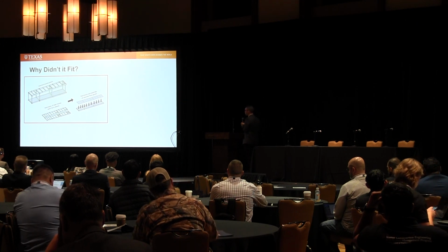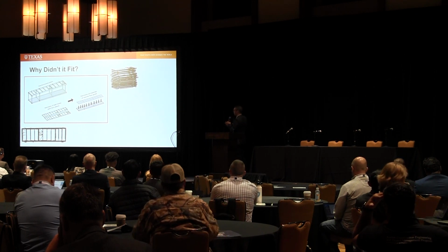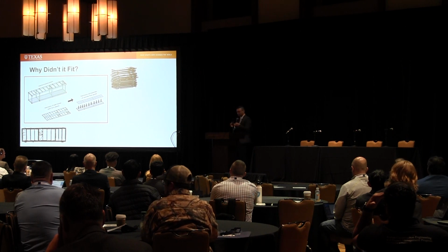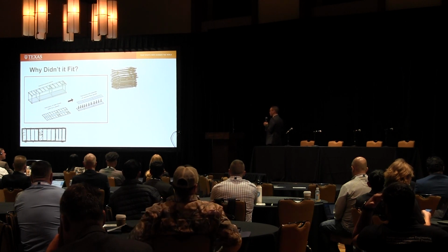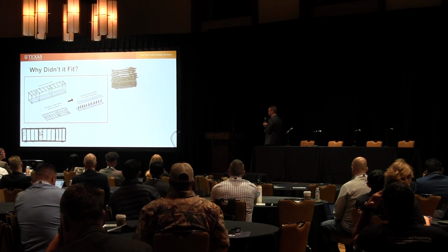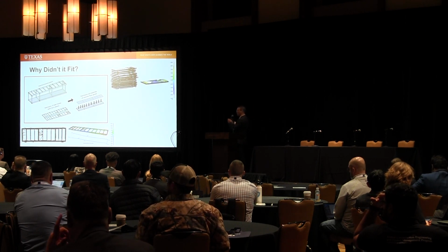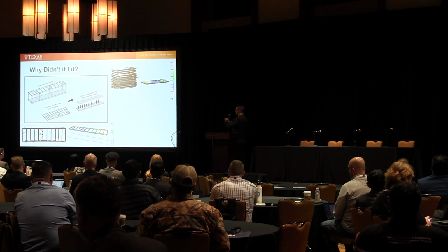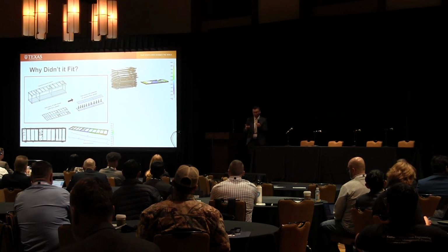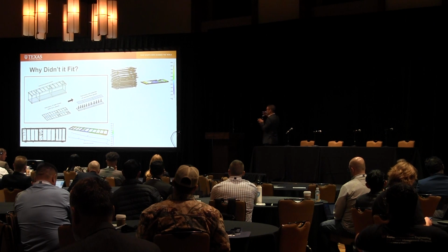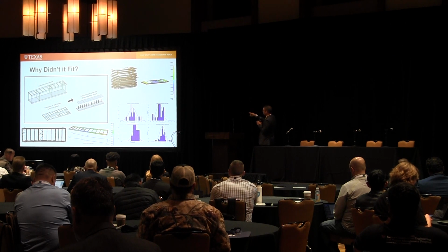And so in another project that I worked on, there was a contractor who was trying to install these floor cassettes into a floor frame and was finding time and time again that there was some sort of misfit. And after exhausting what we can measure with a tape measure, we were not figuring out what was going on. And so introducing scanning into the equation allowed us to understand that it was actually the welding process. In this case, how the frame was being welded was causing weld distortions that were really hard to pick up from manual measurement devices. And so it just shows that by bringing scanning into the workflow, we could systemically understand and quantify the issues of this fit up.